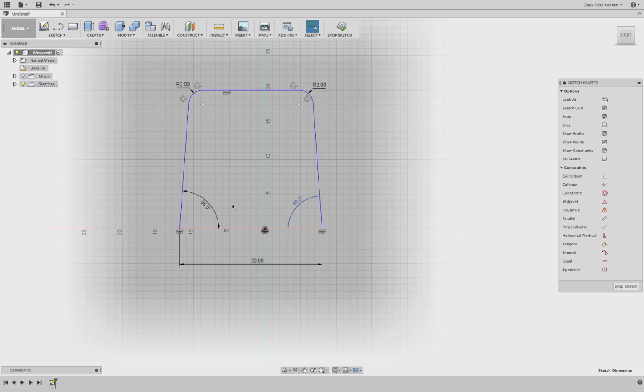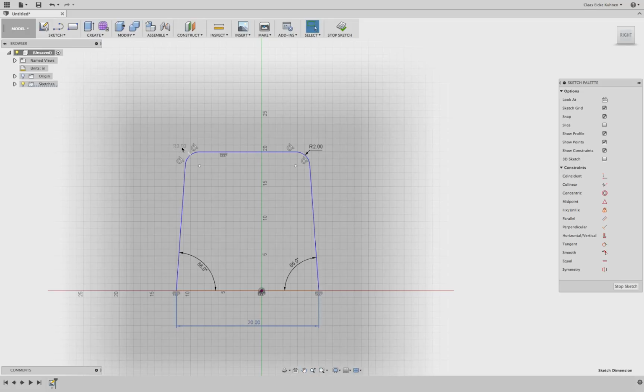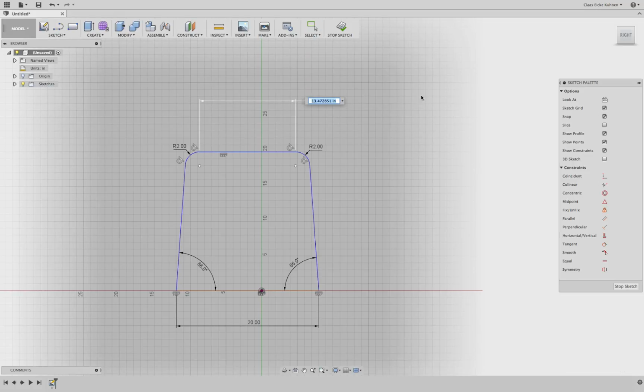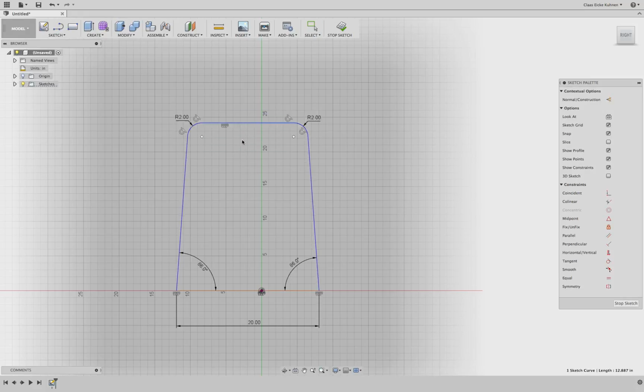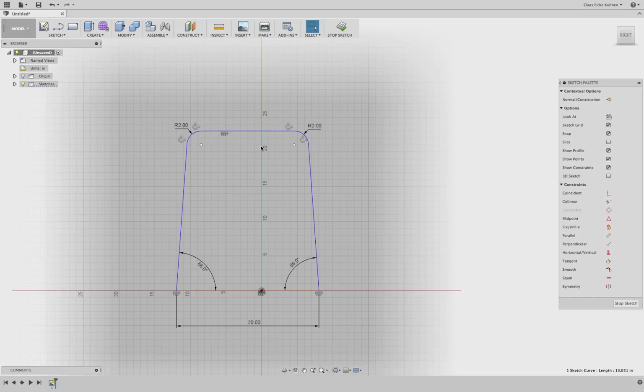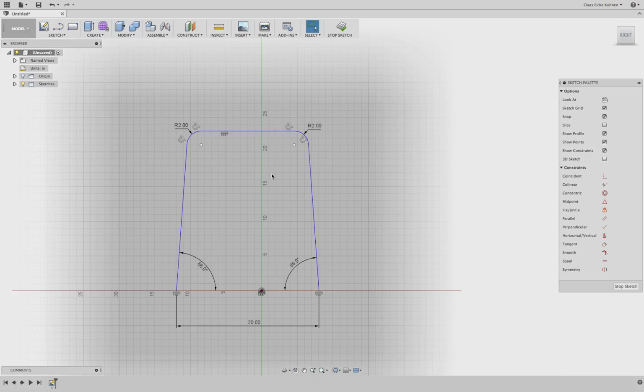So because we have dimensioned the two angles and we have dimensioned the distance between these 2 points, and these radii or arcs are dimensioned, I cannot dimension this one with a driving dimension, but I can read it out right now. Hold on. So I made a mistake. I forgot one point. I can still move this one up and down, which actually scales this object. So this point to this point, or this edge to this point, we have to define.